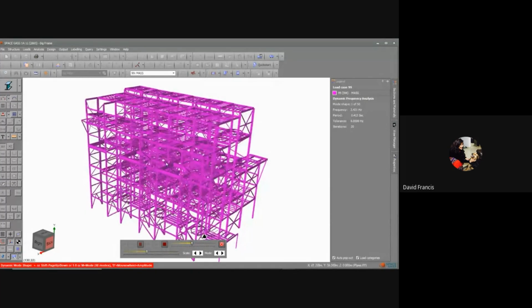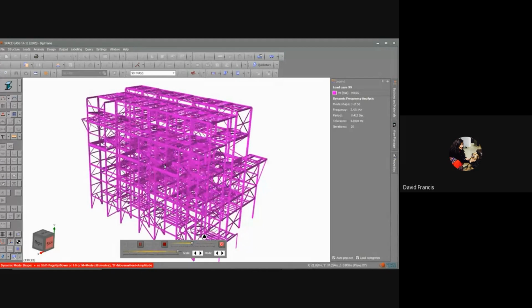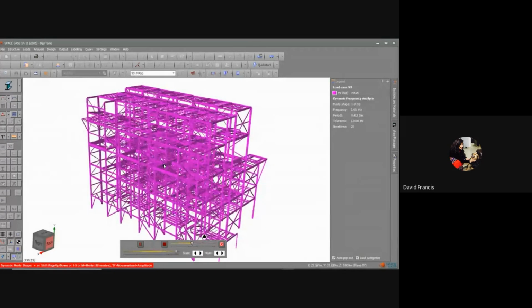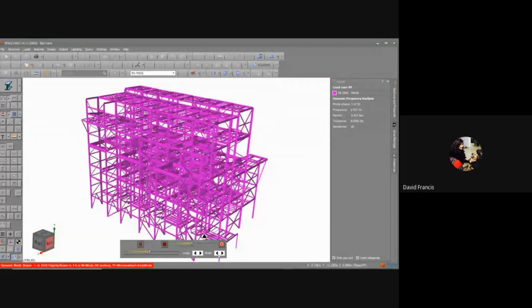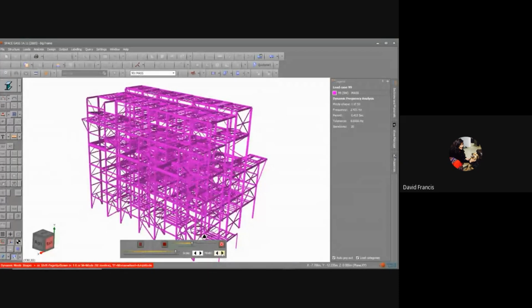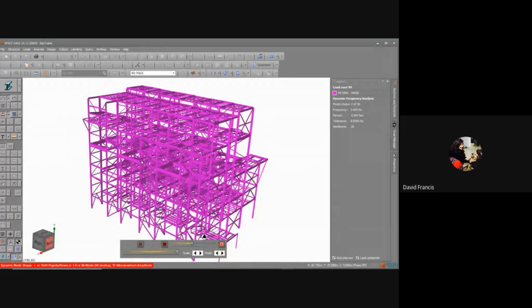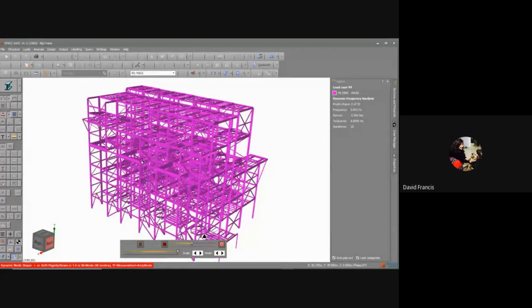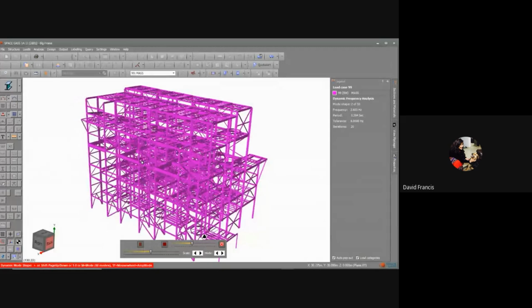in the way. And if I just use the buttons on the keyboard, I've analyzed this for probably, I think, 5 or 6 mode shapes. That's mode shape 1. If I hit the number 2 button on the keyboard, or use the mode increment buttons down the bottom on this little legend, so mode shape 2. And it's really useful because it gives you an idea, particularly when you're trying to explain to your students or to a young engineer,